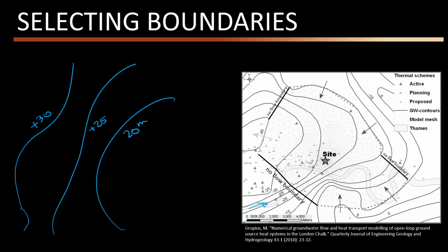If I draw a perpendicular line between these potentiometric lines, technically I can define the streamlines. Okay, so streamlines are nothing but the paths where water moves on.